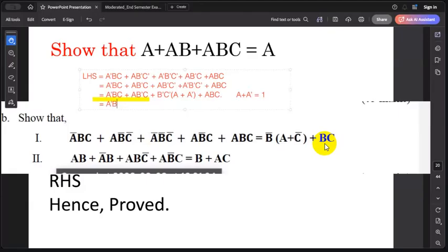So with that verification, we are going to do A bar B C plus A B bar C. Even I'm bringing the other factor also this side. And now we have something like B bar C bar. Only that we have. Now we have to again look for any possibility, right? So B bar C bar is there. So we will check for any possibility from here. You can see in this one, the first expression and the third expression. Does it have any common factor? Just check that. B, yes. C, C is common. Yes.